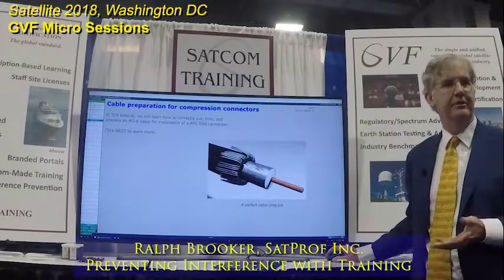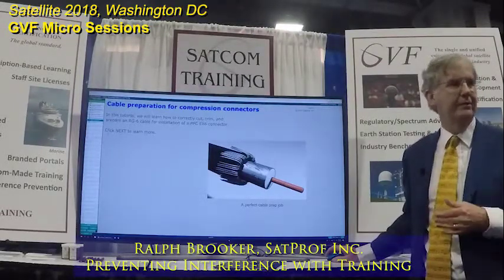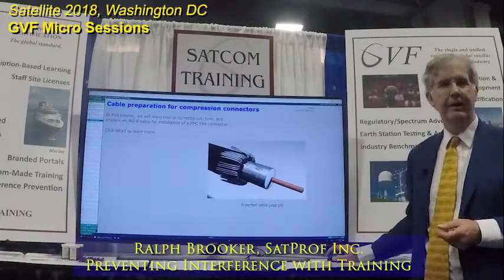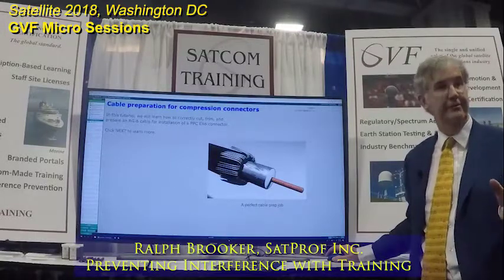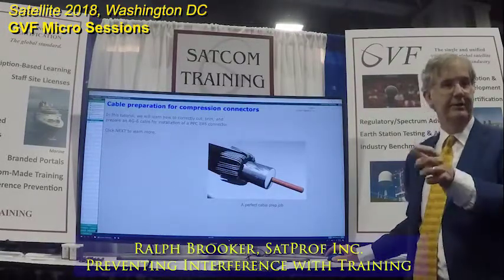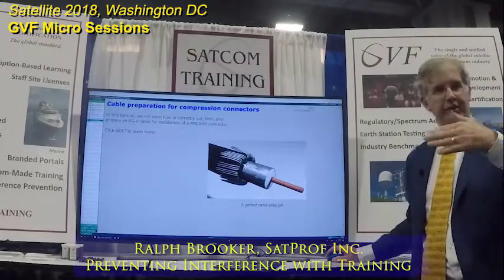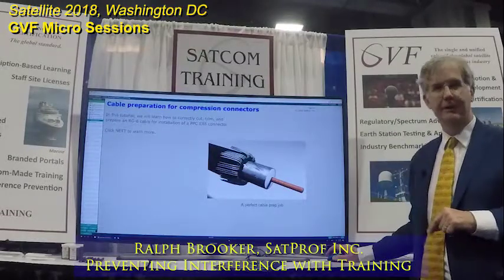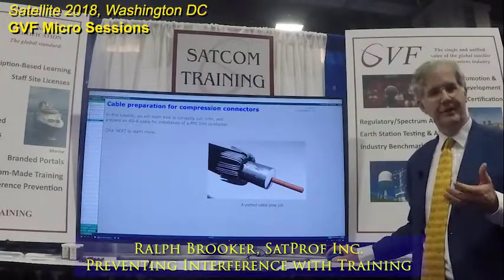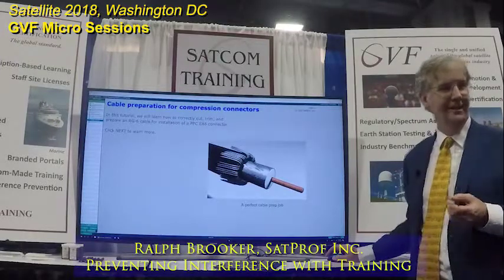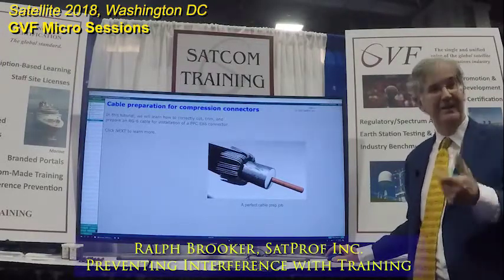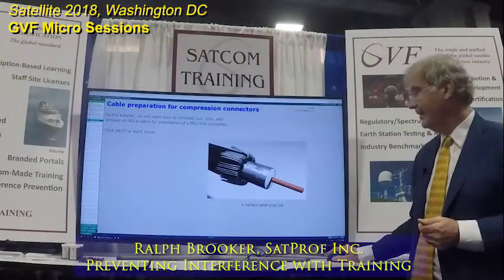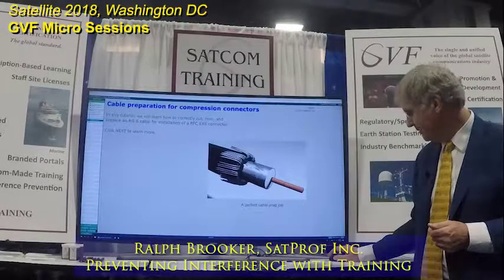It's retransmission of local ambient signals, often from cellular signals, mobile phones. GSM signals will get into a certain part of the IF band, travel up the cable, go to the BUC and the antenna, get upconverted, amplified, and they show up as little interference signals on the transponders. In some cases, satellite operators can even take a cell phone and receive it, and that's how they figure it out. Sometimes they've actually tracked it down by catching the ID signals off the GSM with a phone or a base station.